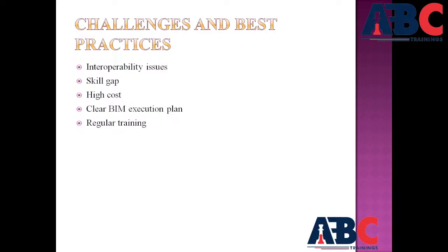So first of all, like any technology, BIM adoption comes with challenges. First one is the common challenge of data interoperability and file management. One of the biggest challenges in BIM is data interoperability, simply getting different software platforms to talk to each other smoothly. Projects that involve multiple tools like Revit, ArchiCAD, Tekla, Navisworks, and others, each of them has slightly different data formats. This can lead to compatibility issues when exchanging files, resulting in lost data, misaligned models, or extra coordination work.